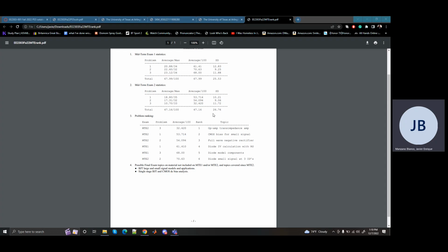I don't know if there's any confusion on what this is, right? Because it's an ideal op amp, the gain is infinite, which means that there has to be very small difference in VP and VN to be multiplied to a certain value. So gain goes to infinity.